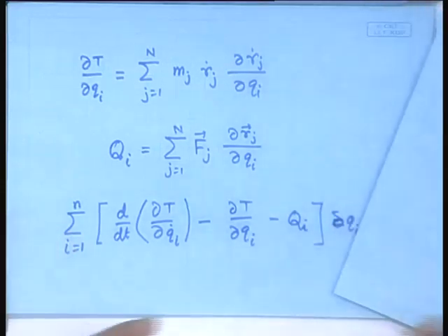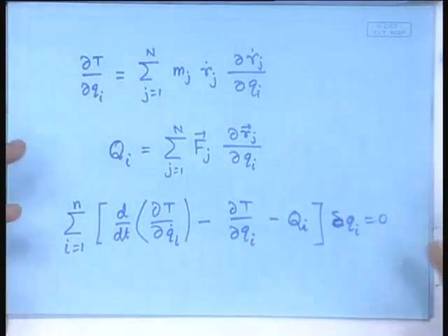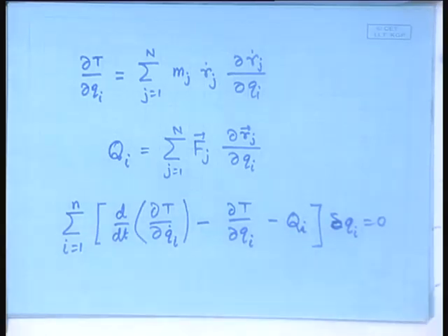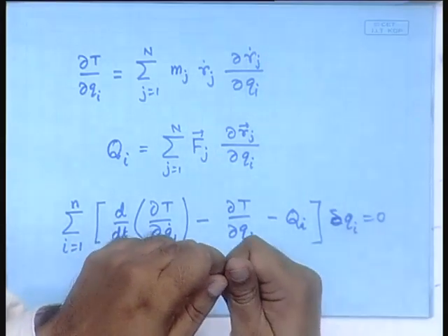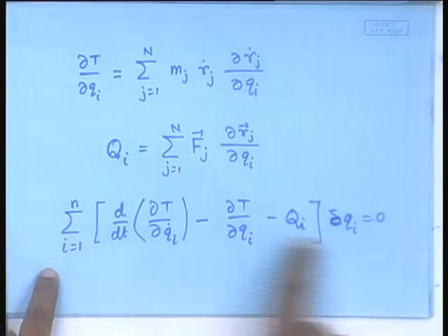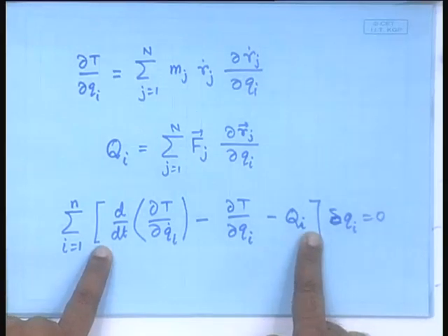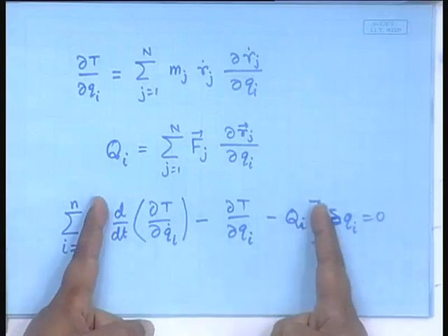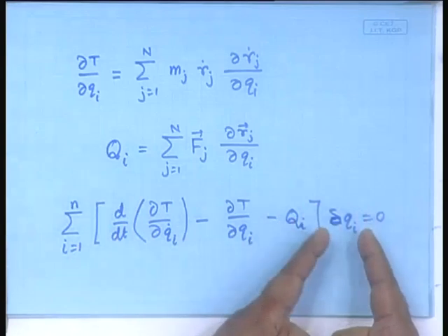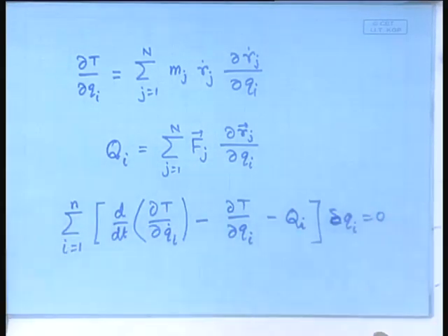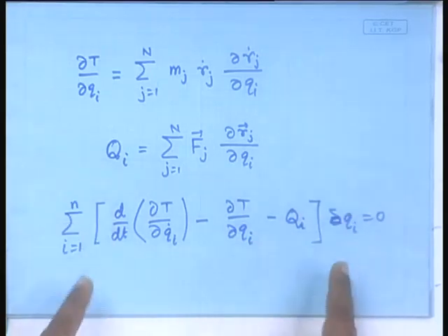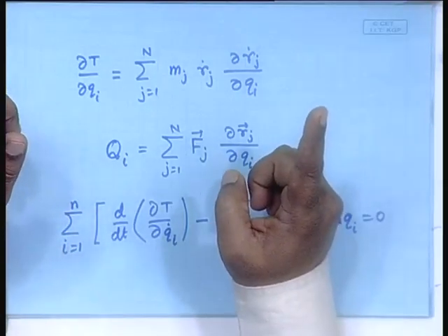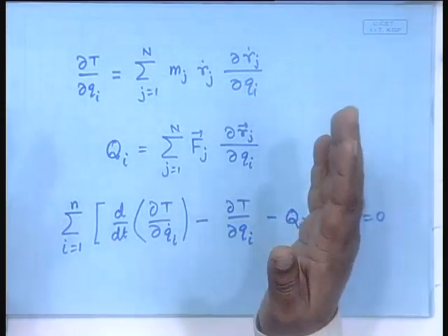So, true that we went through a lot of partial derivatives and messy stuff, but ultimately the objective was to simplify, and here is the simple thing. And you notice that here is something that is multiplied by the admissible motion, and the admissible motion along the first coordinate and the admissible motion along the second coordinate are all independent quantities, and this term summed over i would be 0 only if this term is 0 always. Can you see that? So, here is a term for the ith coordinate, multiplied by the ith admissible motion, and all that summed over has to be 0, and that can be 0 only if, since the admissible motion cannot vanish, this is something that we have assumed can be just any motion, therefore, this term must vanish. Okay. Not only that, this term must vanish for all the generalized coordinates, not the summation, just individually along all the generalized coordinates.